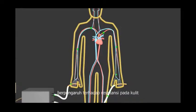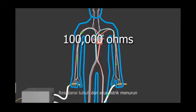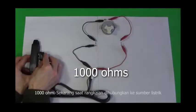And voltage isn't the only thing that affects skin resistance. So does wetness. If the skin is wet, from water poured on it, from sweat, or from high humidity in the air, the body's overall resistance drops from around 100,000 ohms to around 1,000 ohms. So here I replace the resistors so that the resistance adds up to only around 1,000 ohms.